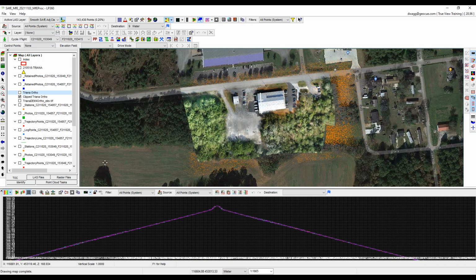Okay, great. And then just in terms of workflow again, you did the strip alignment and then did smoothing. That's the recommended flow. You wouldn't want to smooth before doing strip alignment? Correct. Yeah, we always want to do the strip alignment first. The smoothing is going to look at basically over all the data and then try to fit it, and so you want to get it to best fit first before you do the smoothing. Gotcha, gotcha.